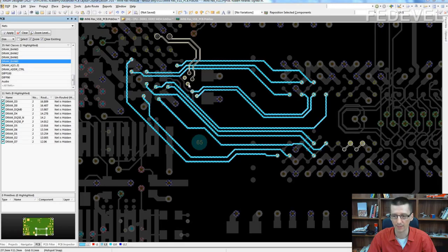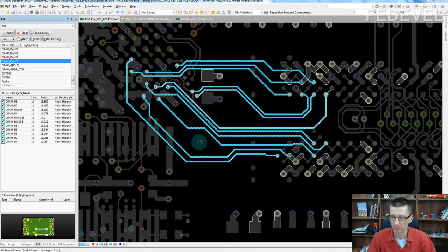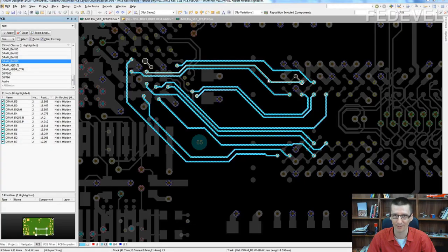We learned that ideally we would like to route these differential pairs together as neighbors. And when you have a look here, this D0 signal is in the way of this differential pair. So we need to somehow reroute this D0 this way maybe. And you may want to change these vias here, or you may want to swap some of these pins. I'm sure you will figure out a way to connect it.